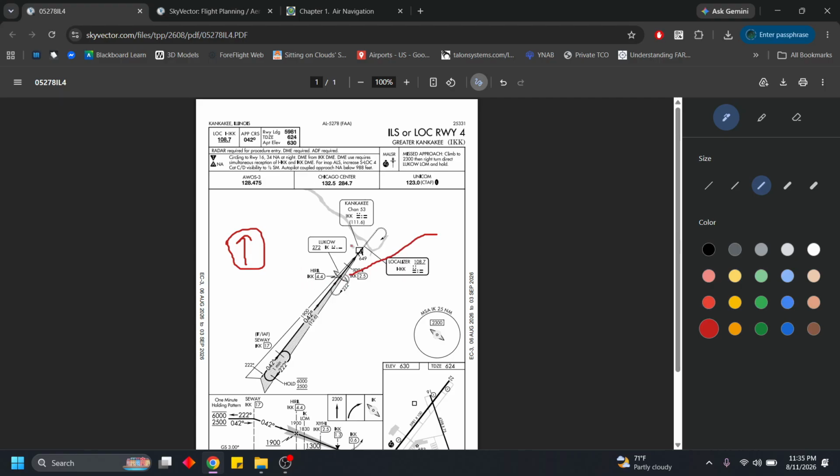Next, we have to be able to identify the fix itself, or in this case, station passage. So we need to be able to say, okay, we are over top this point right here. In a standard VOR hold, you'll notice that it's the to-from flag flip is what we're looking for for that station passage. If it's a DME hold, we're seeing that exact DME measurement pop up. But in this case, we want to see that RMI needle flip all the way around.